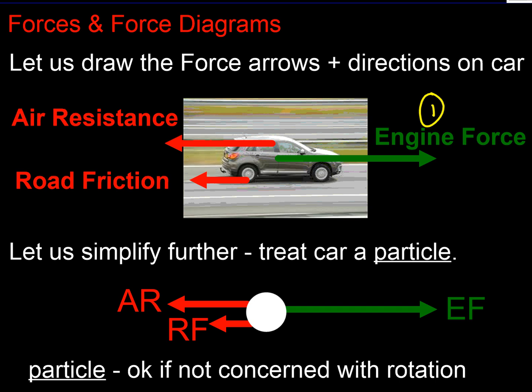And what's holding us back? Well, we've got air resistance. Yeah, we've got pressure all over the surfaces of our car, but actually we just want to say there's one big lump of air resistance. So we're going to treat that as a single force. And then we've got 4 tyres, and they're in contact with the ground, and fronts and backs of them are operating in different ways in terms of load, but ultimately there's some frictional force holding us back, isn't it? That would try and slow us up. So there's our first idea. We've reduced this to 3 forces, and that's going to get us going.